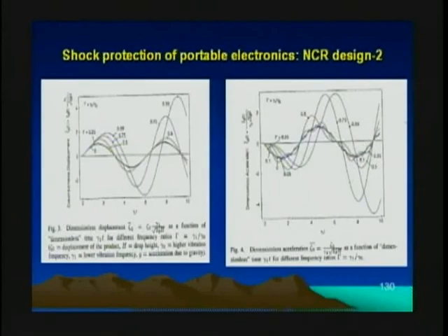These curves were obtained as a function of time, showing how these processes develop. And this system, generally speaking, has 2 degrees of freedom. And if it has 2 degrees of freedom, it has 2 frequencies. In this notation these 2 frequencies are gamma 0 and gamma 1. And if the ratio of the 2 frequencies is close to 1, we have resonant conditions.